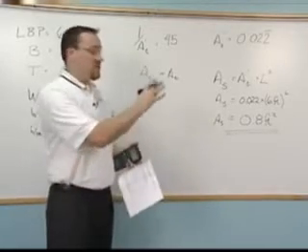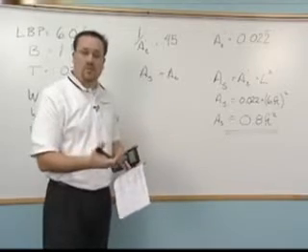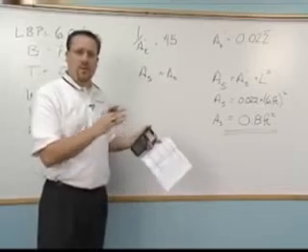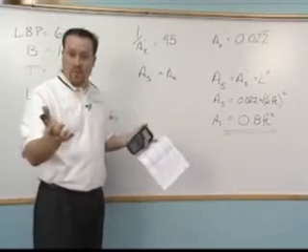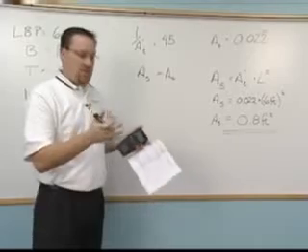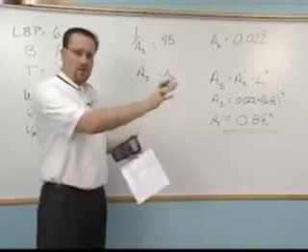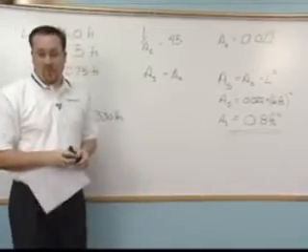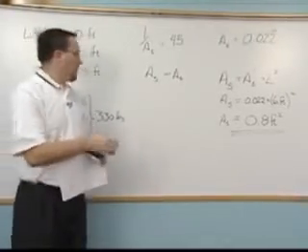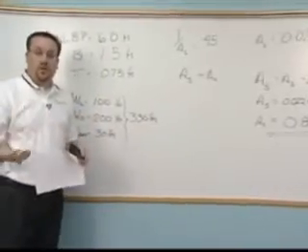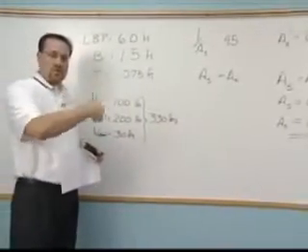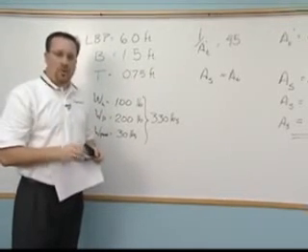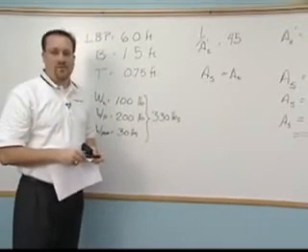Also remember, the first time we did this calculation with the other equation, we found an answer that was 0.1. So this is 8 times larger than the other equation, which was a minimum, as was stated. So keep in mind that you probably should be somewhere between the first equation, the 0.1 answer, and this answer, the 0.8 square foot answer, for the size of your rudder for a ship with these dimensions. Now, of course, you'll be doing this multiple times as you go through your design spiral and these dimensions change. But it's a good rule of thumb, and hopefully it will get you well on your way to winning the maneuvering portion of your competition. Good luck.